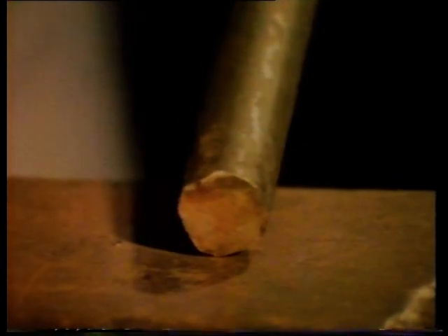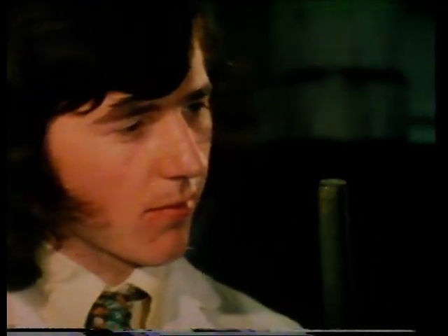This piece of cold, mild steel isn't a very malleable material. It can't be hammered into shape very easily. All that effort and hardly anything to show for it. In this forge, we've heated a similar piece of steel until it's a bright cherry red in colour. That's well below its melting point. Let's see if that's made any difference. By raising its temperature, we've made it much more malleable. Steel is often heated to increase its malleability.